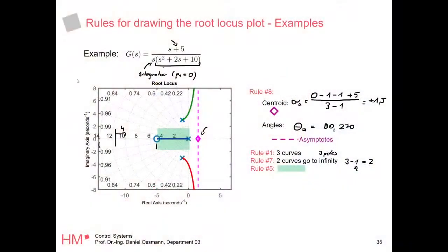In this case, we have an integrating system, second order lag, so a PIT2 system. So also this guy at some point gets unstable, and this is kind of a problem because this system per se is not stable, right? Because we have a free integrator, so we need proportional feedback to stabilize it. So this guy moves to the left, then we are stable, but we cannot move the gain up very high because we are immediately crossing over.